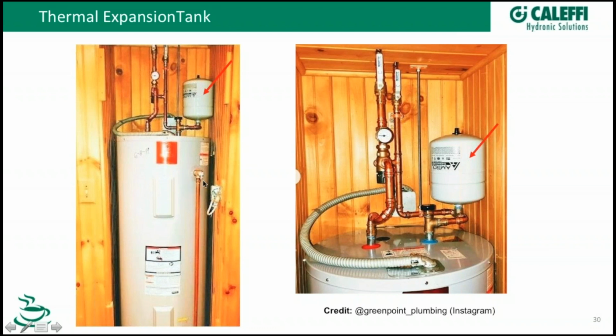Now, most of the residential ones start pretty big, I think at 690,000, so it's rare to find a domestic tank with a higher BTU capacity than that. But more importantly, on commercial buildings where you might have a big burner, high output water heater like we showed on that very first slide, you've got to make sure that you're putting the right relief valve on there for the application.